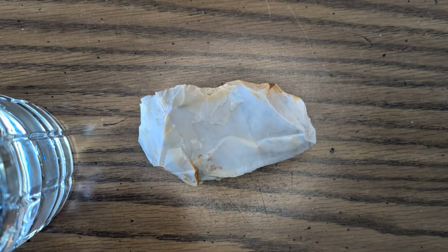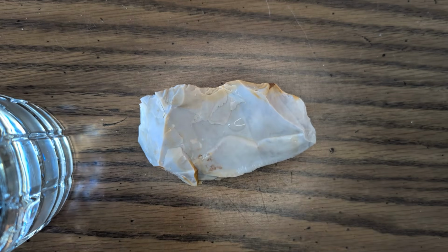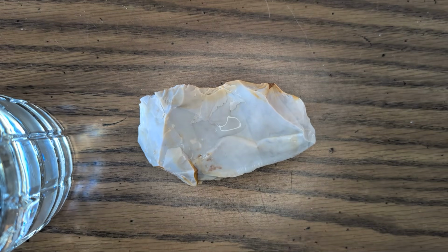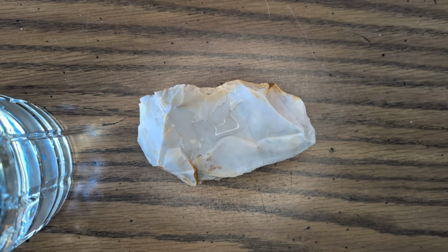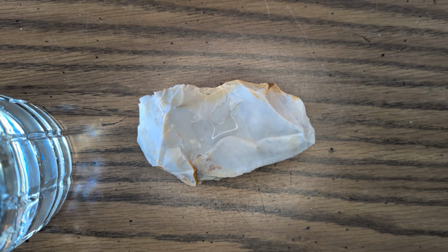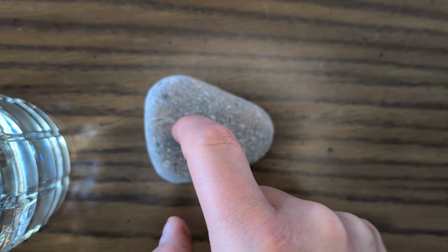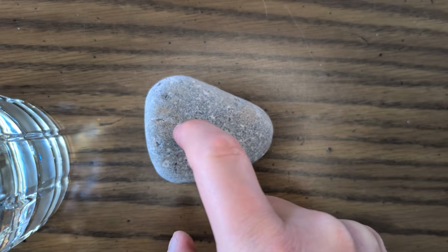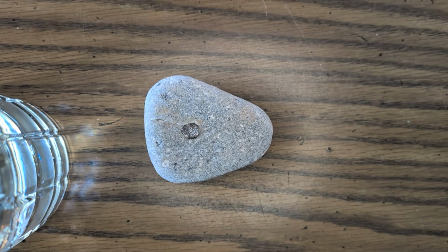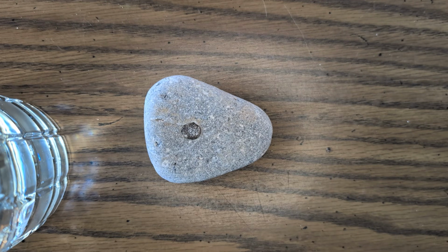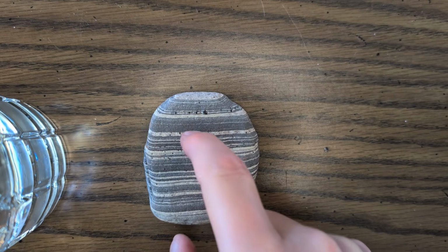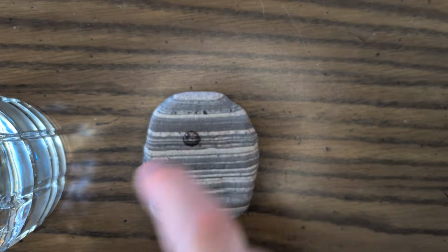With chert, if it's unfractured, you've got a similar situation, similar hydraulic conductivity. If there was no such thing as evaporation, you could spend your entire life waiting to watch this water soak into the rock. It would eventually, but it would probably take longer than your lifetime. Limestone has a much higher hydraulic conductivity, but still relatively low. For this droplet to penetrate 1 centimeter in the rock will take about a full day. Now that's different if there were cracks in the rock, and if there's a cave network, it would flow through instantly.